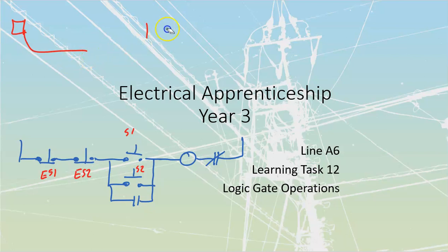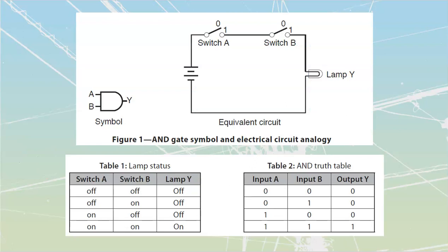What we're going to do in our systems is we're going to have just a single hot line that we're going to take around. We're going to run it to each of these devices and back to our PLC, and we're going to program inside of that. Let's start by defining the components, then we'll define what we utilize these things for.